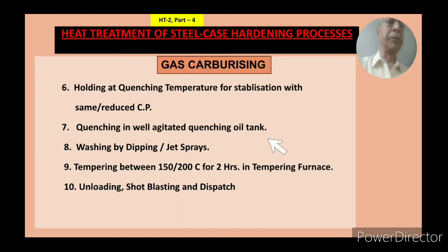If your transfer time is delayed, then it will be a delayed quench. Sometimes it happens in practice that you are shifting the load and in between the crane has some problem, an electrical issue, and it's stuck there, but still you go and quench it. That is not desirable. You will not get a good surface hardness and good microstructure. So quenching time has to be as quick as possible. Okay.